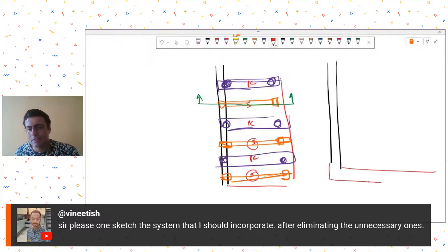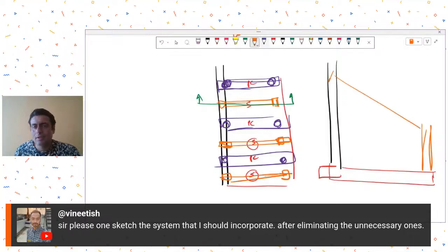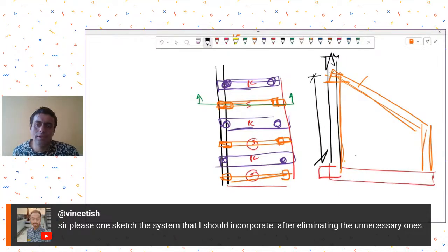This is my thinner toe heel slab that I'm providing. From this, I just take this column, maybe tie it like this. You check whether that frame has to be provided right till the top, this tie element, or maybe somewhere at mid height. You can introduce one more column over here if required. So this forms a stiffer system like this. The height of this you try and iterate and see which height looks okay.